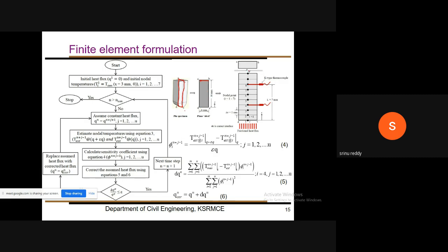So this plane only. For the nodal points, for magnifying, I have given one node at each mm, like nodes I have measured, indicated here. First node, second node, 7 mm, right? 7 mm means we'll get 8 nodes from bottom to top. So the fourth node is at 3 mm. At the fourth node we have measured temperature, and at the seventh node we have measured the temperature. And the heat flux, the frictional heat flux that we are giving inside, is at this contact, at the face of DC. So if we can understand this model, further it will be easy to understand.